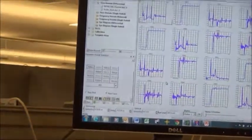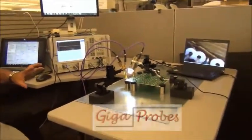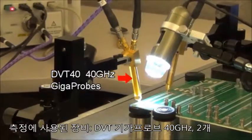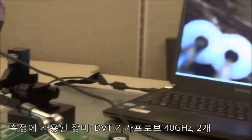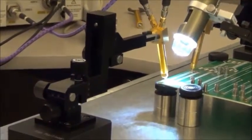On the probe setup, we have a very nice, easy to set up system from Gigaprobes. We have two differential probes working up to 40 gigahertz with a small camera system and magnetic bases, and you can see how we get coplanar probe placement on a differential PCB trace with our system here.